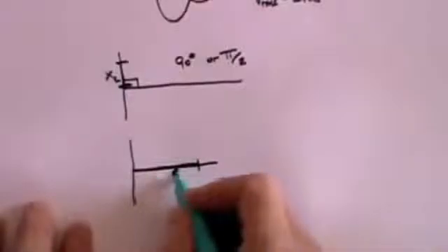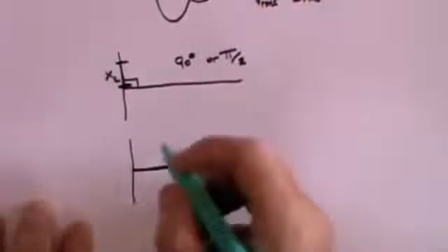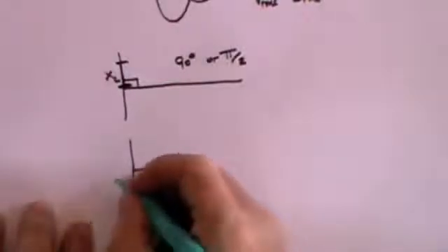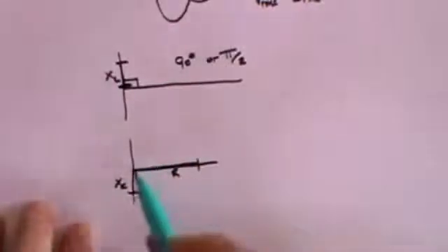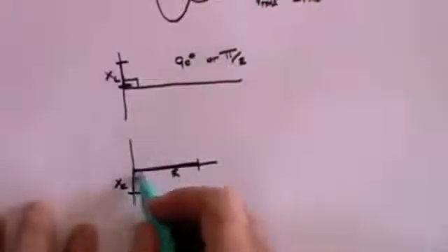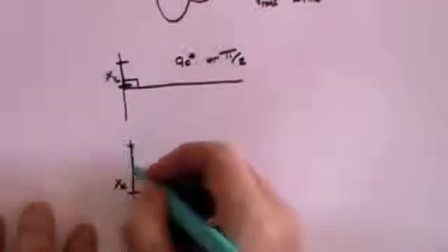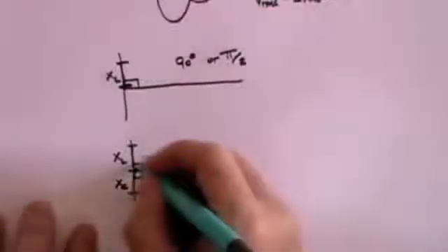So just to recap on the phasor diagrams, if you're drawing a resistance, it will be R in this direction with a phase angle of 0. If you're drawing a capacitance, then the reactance value is the length of that line and the angle is at 90 degrees. And if you're drawing an inductance, then the reactance effect is the length of that line with an angle of plus pi over 2.